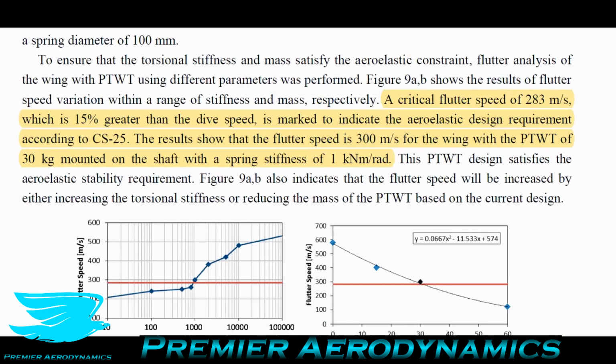So they go on to the critical flutter speed. Flutter, which I covered in that podcast talking about 3D printing for aeroelastic purposes, is where the wing will start vibrating and then it'll get more and more violent to the point where the loading is just so great that it'll snap off. And that's not good.